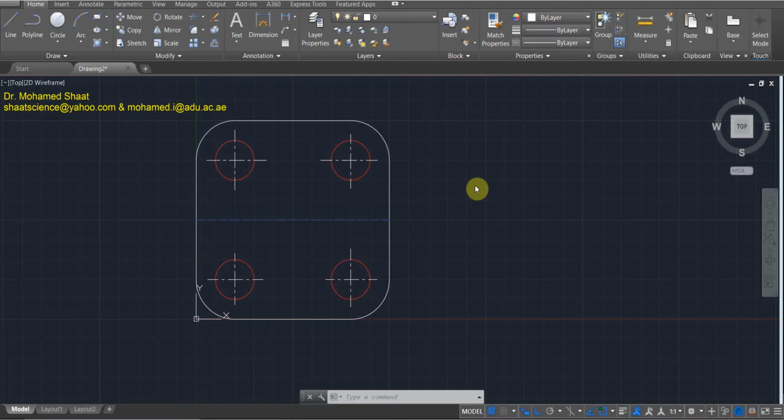So add all the dimensions to all the objects, and don't forget any dimension. It is highly important for a completely defined engineering drawing, so somebody else would be able to use this drawing or work further on it. So it is highly important to know how we can add these dimensions, whether using AutoCAD or by hand following the standard. And the standard that we're going to use again is ISO, as I'm going to show you. Also, it is highly important not to miss any dimension.